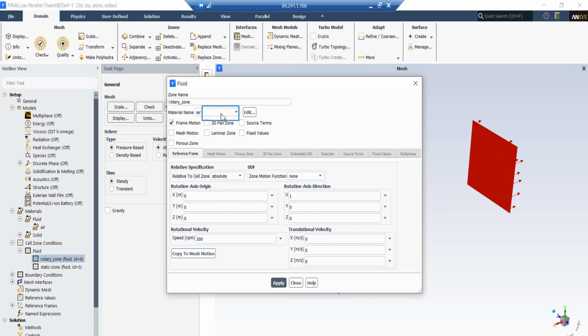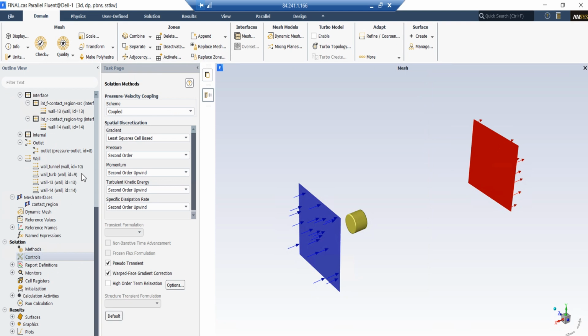Also, for our stationary zone, that is the zone corresponding to the big rectangular zone, there is no need to adjust any other setup for the current simulation. Finally, regarding the choice of our discretized variables, we must always end the solution with a second order accurate discretization. Why? Because our equations themselves have been defined by second order derivatives. So a first order approximation would lead to a highly dispersed result.